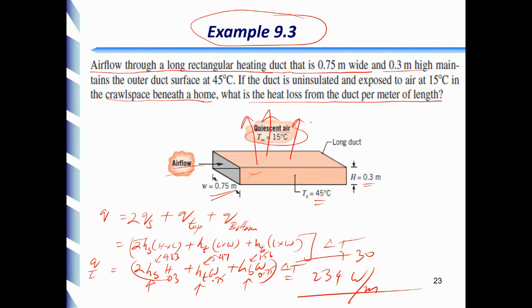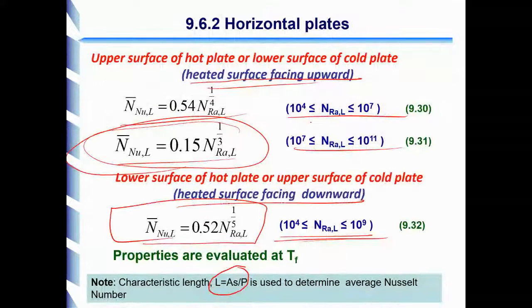It is when horizontal plate. In horizontal plate, you see the note here, use characteristic length. Only when it is a horizontal plate, then use characteristic length.